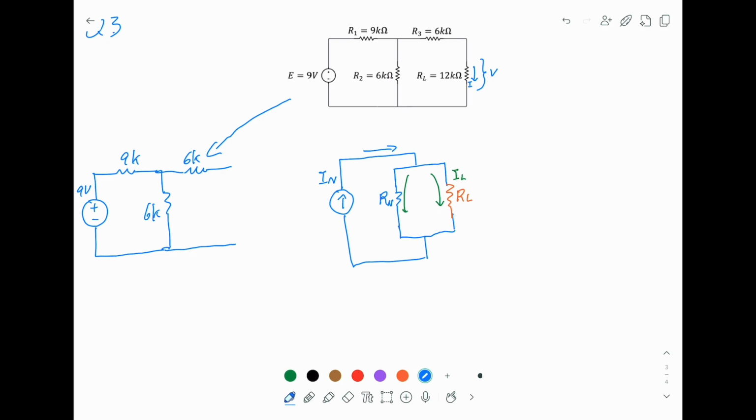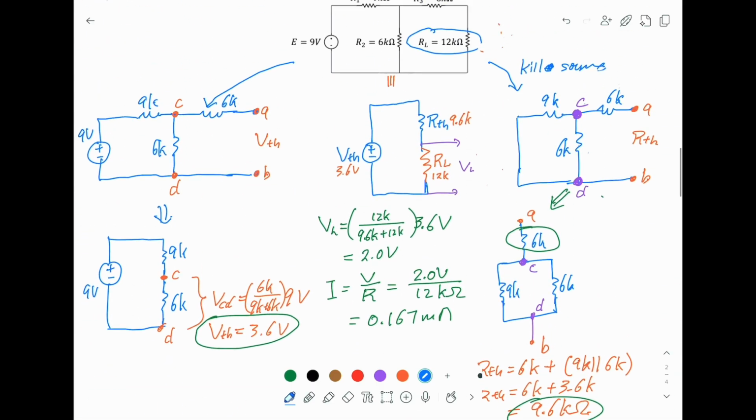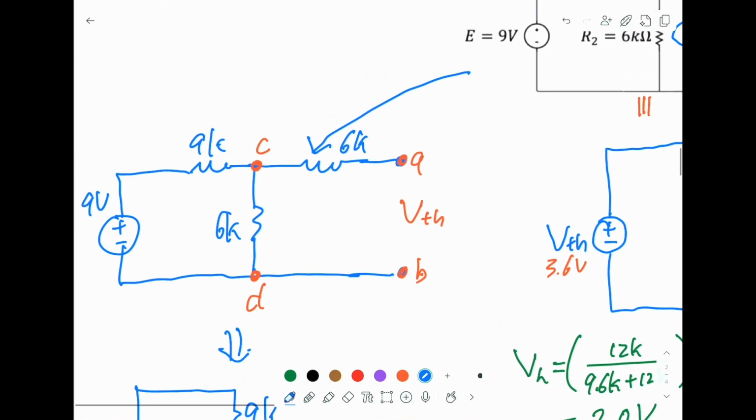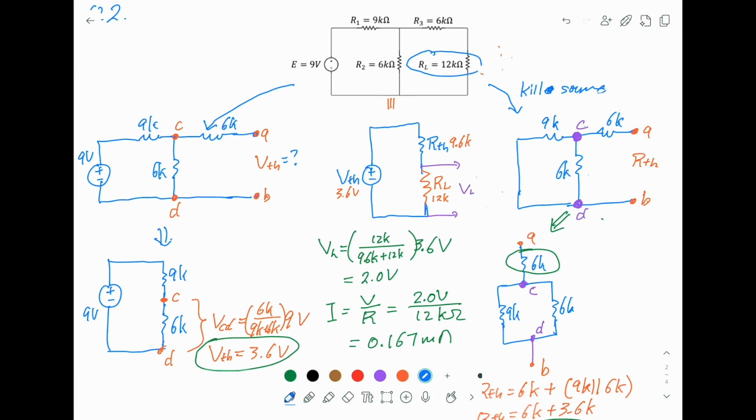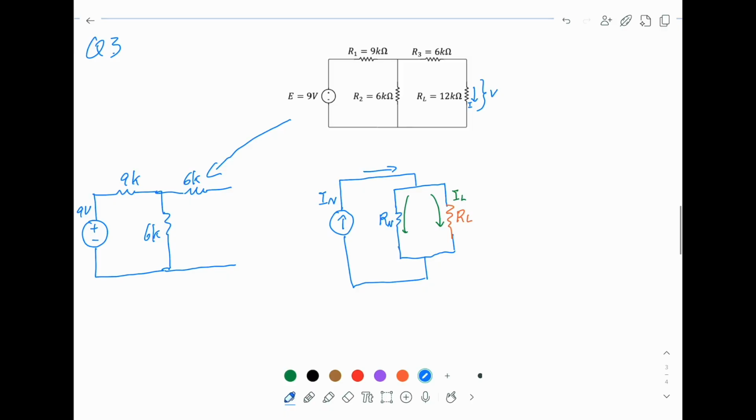In Thevenin, we just remove the load resistor, and then we say what is the voltage across it. Just recall, this is what we do. We remove the load and ask what it is. But this time we need the current. So yes, we will remove the load, but at the same time, we must reconnect this one, give a path, and we want to find what is the current passing through this point, and we call this IN.